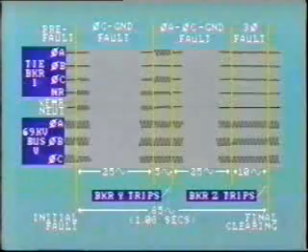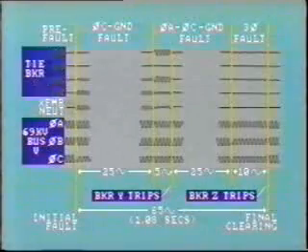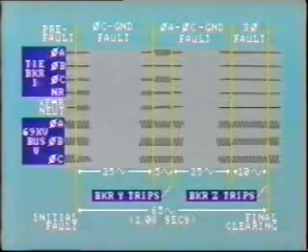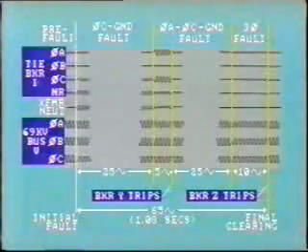The oscillograph has recorded 69 kV bus voltages in all 3 phases, neutral current in a grounding transformer, and current in the bus tie breaker, all 3 phases as well as the residual current. The total elapsed time between the initial fault and final breaker clearing was 65 cycles, just over 1 second. Notice that we have broken the traces to indicate where the waveforms just repeat themselves. After 3 cycles of pre-fault recording, we see the onset of a single line-to-ground fault.